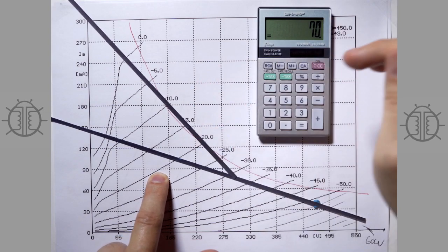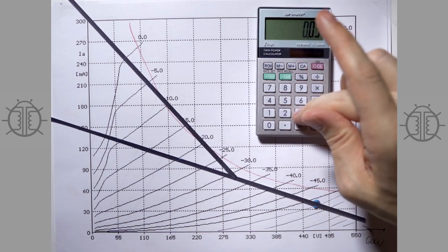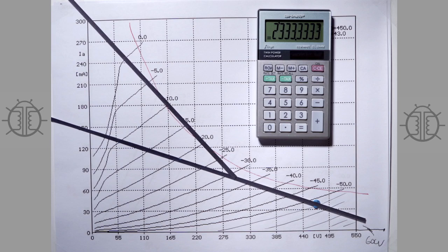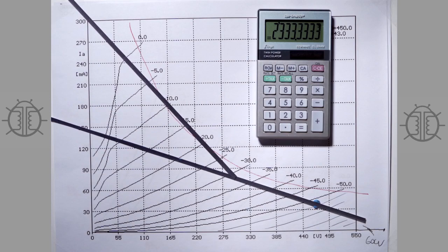We need to source 30 milliamps, so we'll divide this by 0.03 equals. And so you can see that our plate impedance has gone up from, what was it, 1.8K to 2.3K output impedance. So that's the price you pay for the greater power output. But still, that's not so bad. So you can see why ultralinear is a good sort of compromise.